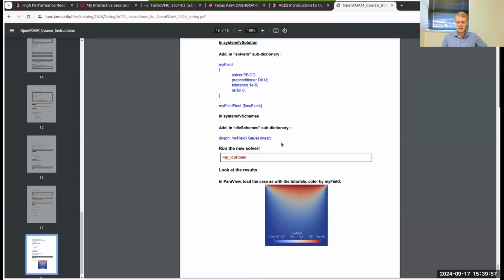And as you could see how to implement an equation, probably the equation that's suitable for your research is a little more complex than the one I picked. But OpenFOAM's modularity and the finite volume methods that come with it make it very easy to write out the equation that you want, and then compile it and run it as a custom solver.